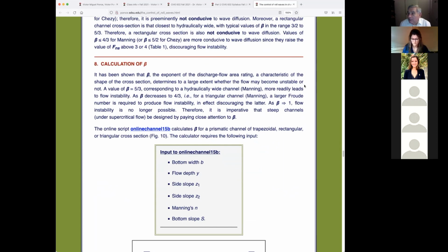I went to Bolivia to gather facts, data, pictures, videos, and so forth. Then I came back, studied it, and realized it's a simple matter. All we need to do is generate a rating in a prismatic channel, which we do all the time, and fit a power function to the rating to get the beta. Sure enough, that worked beautifully, and we did it all in the calculator.